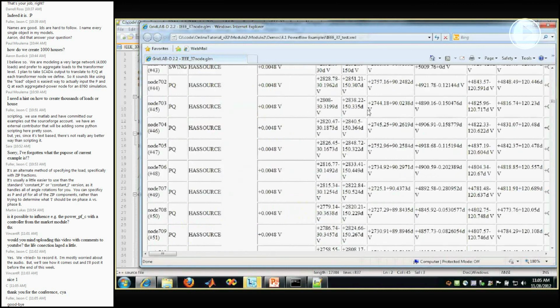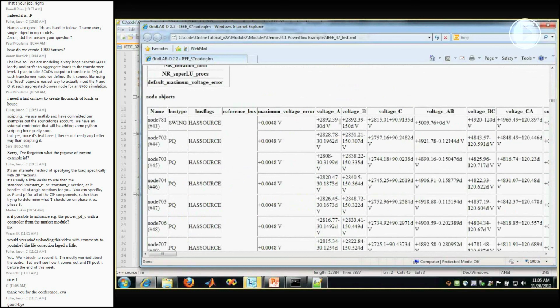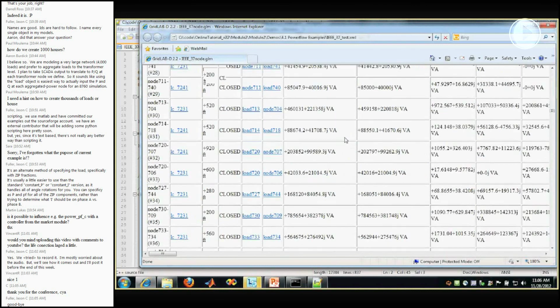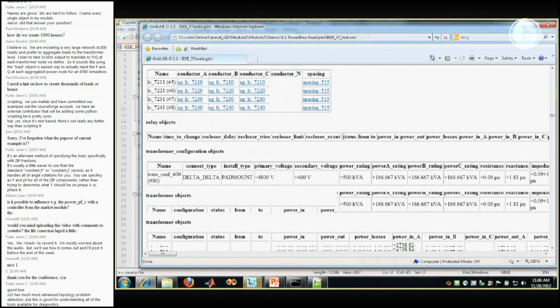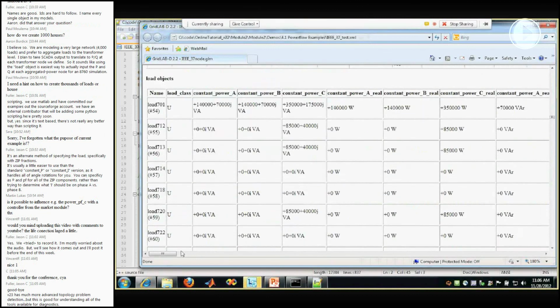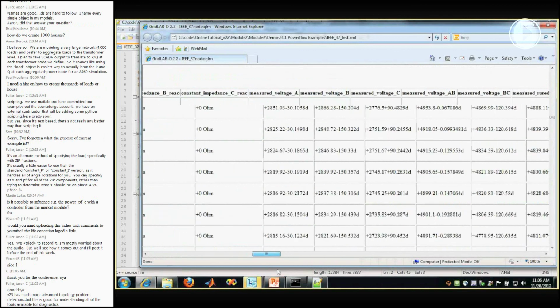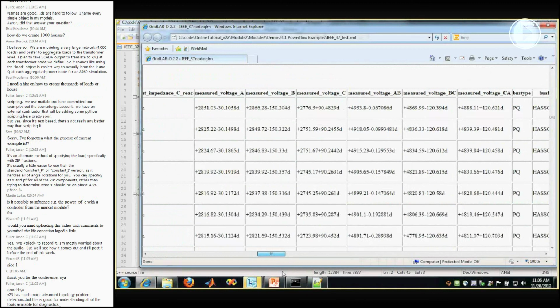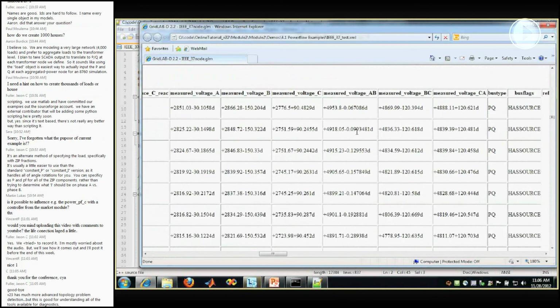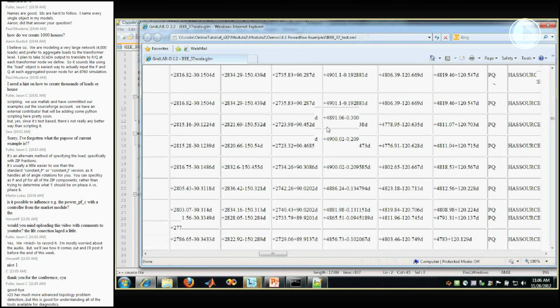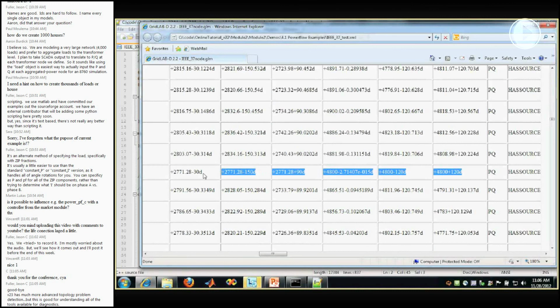So to find out where the breaking point is, we can find one that looks like it's setting itself to the nominal voltage. We know in advance that this is actually a load, because the comment on the top says the line is missing between two of the loads. But we can go down here. Once we find the voltage column, there it is, and we'll look for any of them that have very nice round numbers. Like this one. That is very suspicious, that they have exact numbers for the degrees.